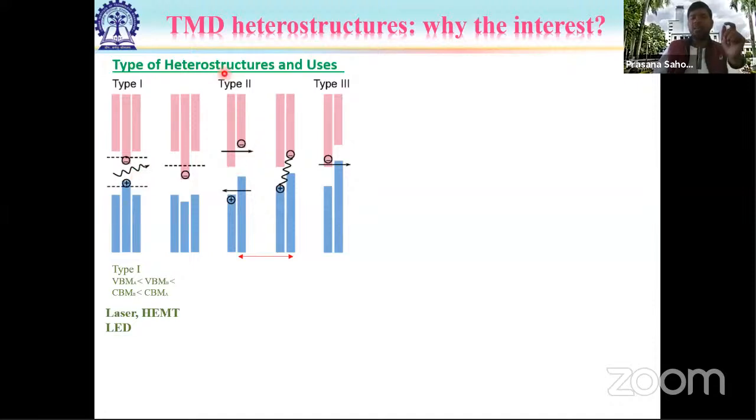And for a solar cell, your band alignment should be like that. If some of you have a chemistry-related background, you know that in chemistry terms, they always correlate with the normal hydrogen potential. It's a similar way. How the potential positions or the band positions are aligned will determine how the carrier will transfer from one material to the other side, or how effectively that will occur. Okay, so there are different ways we can arrange materials.